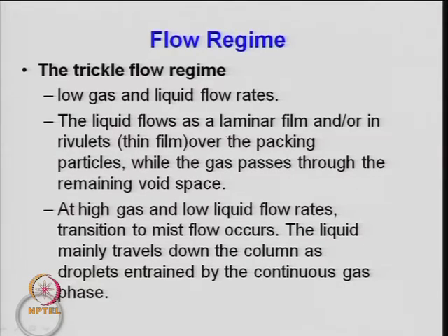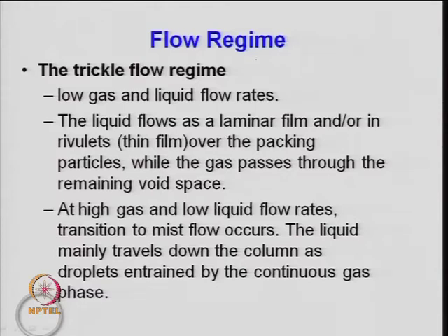So, basically I will talk about the mass transfer control region a little later, as I said before. Here, in this case of the trickle bed reactor, the hydrodynamics is very important, which is governed and discussed based on the flow regime you get in the trickle bed reactor, depending upon the flow rate of gas and liquid. As I said, the trickle flow regime will require relatively low gas and liquid flow rate. Liquid flows as a laminar film.